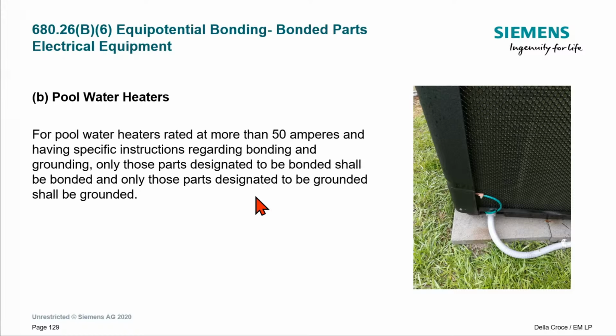The other aspect, the grounding, say through an equipment grounding conductor, that's going to be its function, and that's part of the equipment that runs into the equipment. That's going to make the connection into the equipment. Keep them separate when it comes to pool water heaters. The key thing is do what you need to do for the bonding. Now with this one, I guess the 5 feet doesn't matter, because this is part of heating.